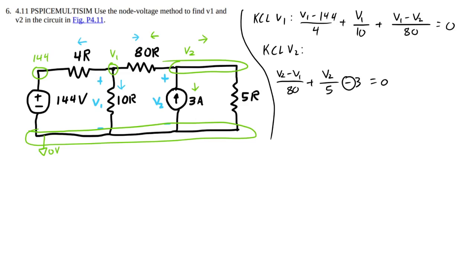And why minus? Well, it's because the little arrow here is in the opposite direction of the current flowing into it. Now, since we don't have an equation that models this component in terms of the voltage drop, we can't flip the sign basically like we can here. So we're just going to leave that as a current.